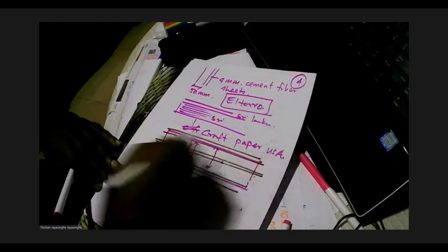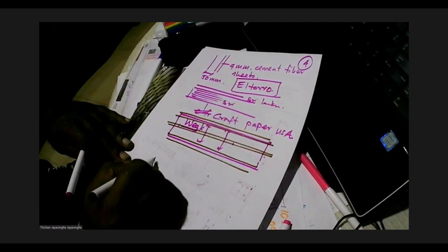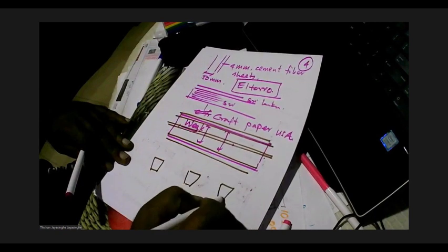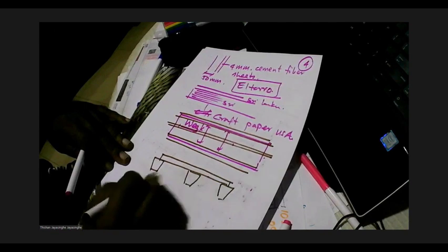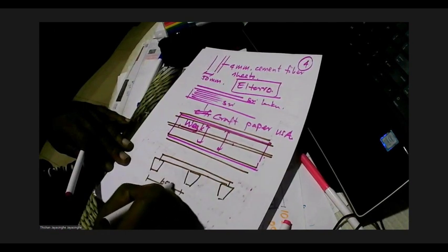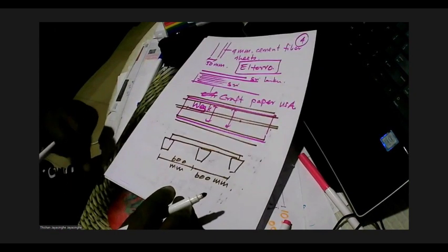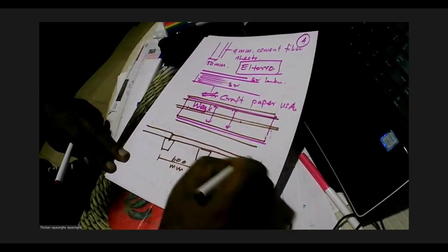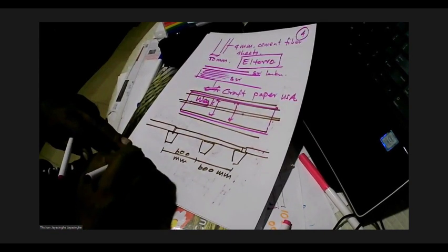support it here. So if you have a Dura panel on a precast beam, like this third system beam, and support it like this at every 600 millimeters, you can get a pretty strong floor like that, and this can be very cost effective as well.